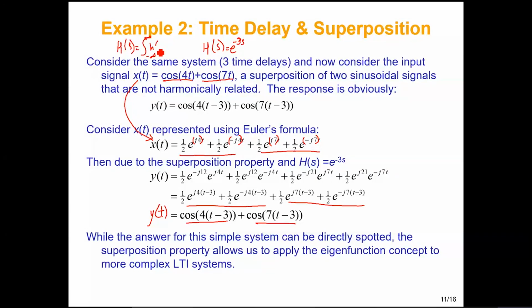So it is basically your integral of h of tau e raised to the power of minus s tau d tau, and it is basically going to be a function of s. The result that you get for this h of s would be some function of s, and this will be the property of that system.